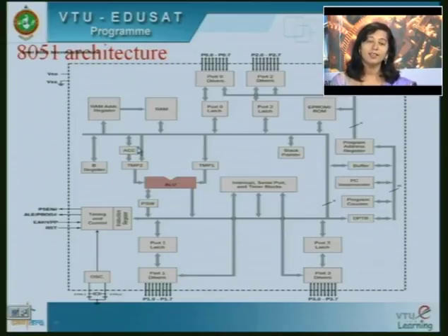Then the output after computing addition or whatever is passed on to a temporary storage register, TMP2. So you can fetch data from the RAM, pass it on to the accumulator or the B register, maybe 2 different data to each of them, add them, subtract, do whatever, and store the temporary result in this temporary register.